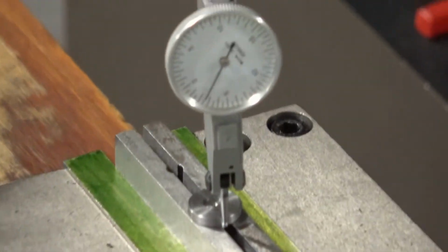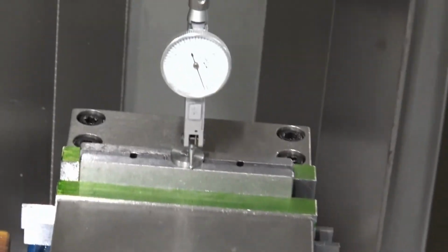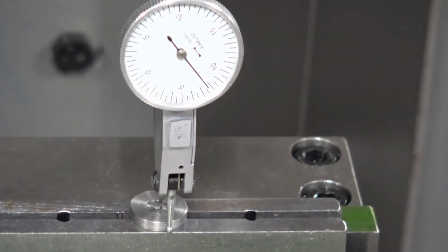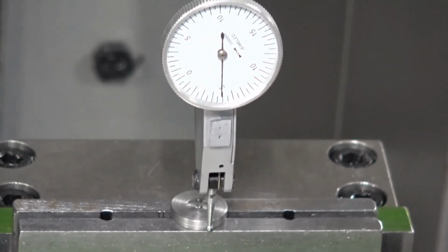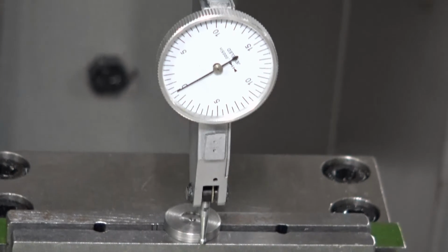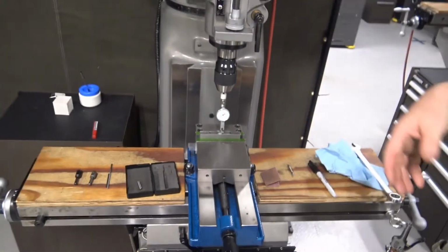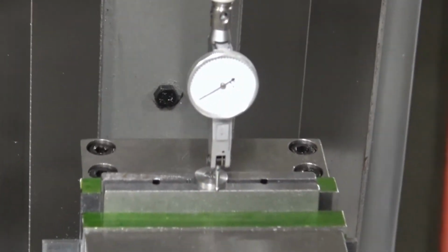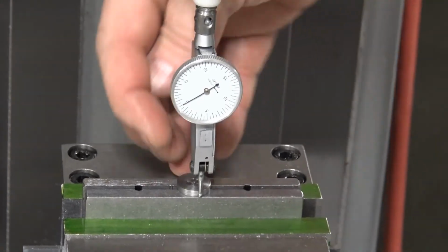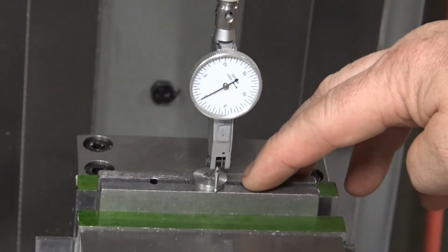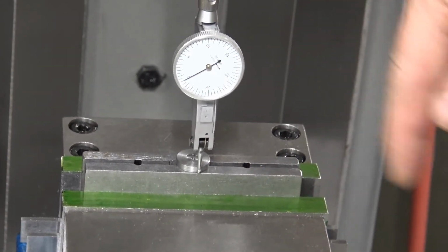I'm going to come back to the 6 o'clock position. My 6 o'clock position obviously doesn't match at 0. So I'm going to move my table. We're going to just run this machine like it's an Etch-a-Sketch, okay? Both handles moving, and I don't care about which direction I turn the dial. I just want to dial it in so it reads 0 all the way around, okay? Well, now that I've set my front, we should all agree that if I get 9 o'clock, 6 o'clock, and 3 o'clock all reading 0, and this is a circle, right?